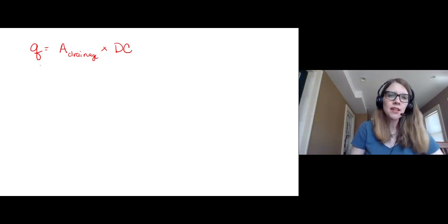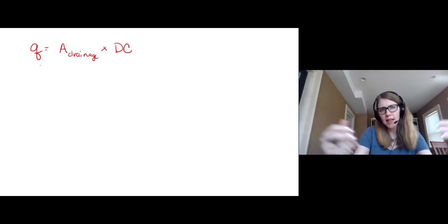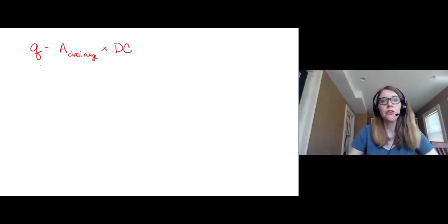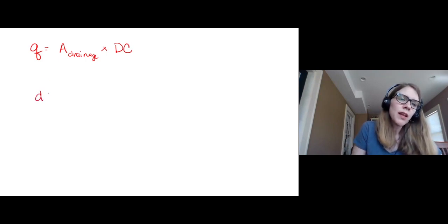And when you put all those things together, those of you who have taken a fluids class, maybe towards the end of that class, you got into open channel flow and you were introduced to the Manning's equation. This is the same equation that we might use to design a grass waterway. It's how water flows in an open conduit. But if we apply that to the drainage situation, we end up with an equation that looks like this.